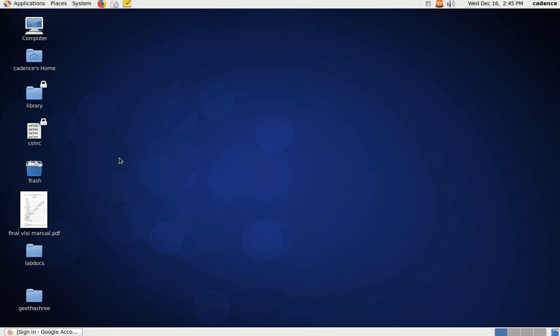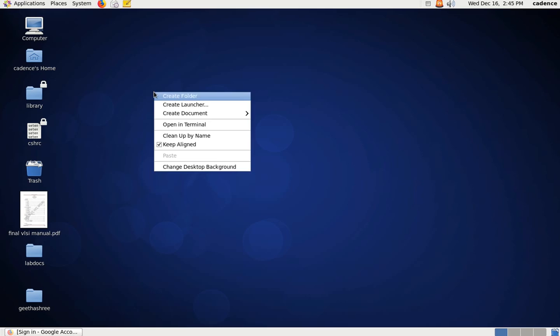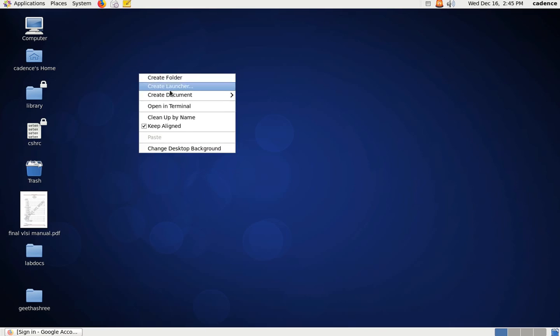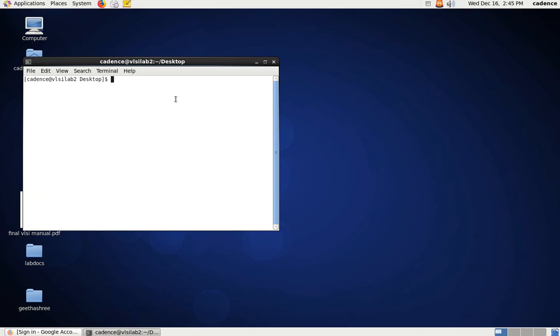So, hi everyone. In this video I'm going to explain the basic common source circuit where the PMOS is used as a current load or active load. First let me invoke the Cadence tool. Just right-click and go to terminal. First invoke CSH, then source the Cadence CSH RC.